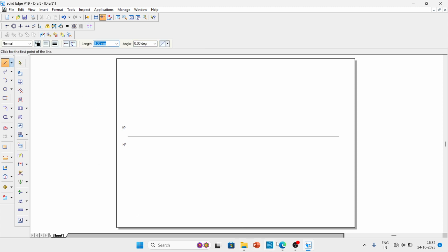Next, it's given that length is equal to 35 and breadth is equal to 25. So just click on a point somewhere here. This is equal to 35. We can use some tricks here, so you need not touch the mouse or the keyboard, and you need not struggle to set a proper rectangle. Here you can see a blue selected option. Click there, 35, enter. Here it will shift to the angle option, where you have to enter the angle. The angle must be 0. Enter. The line has been drawn.